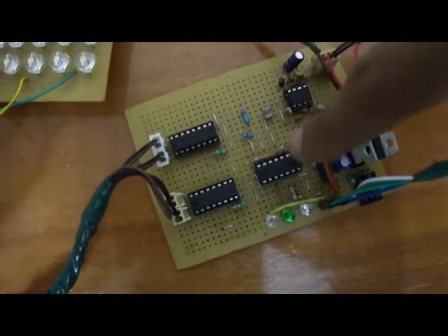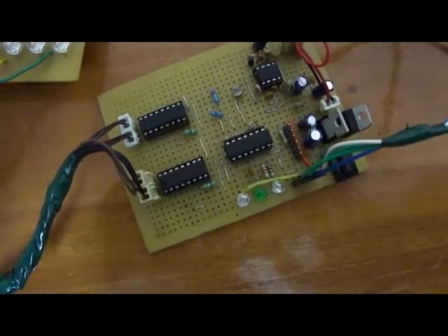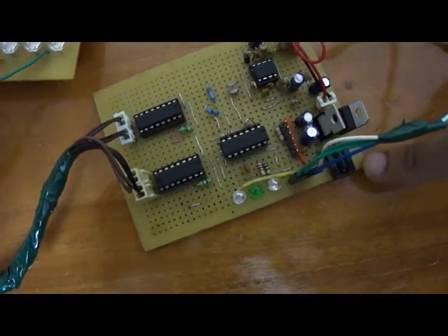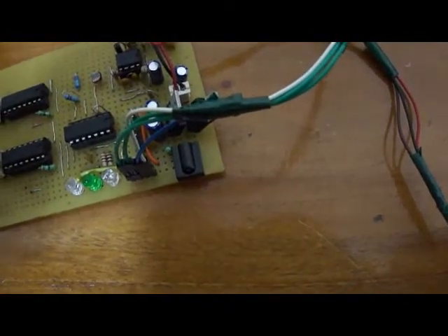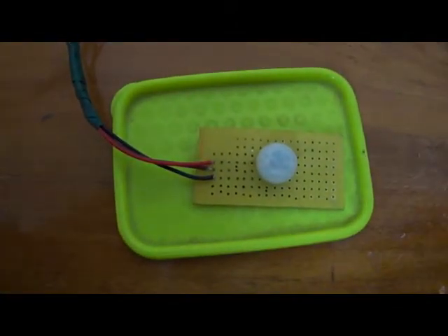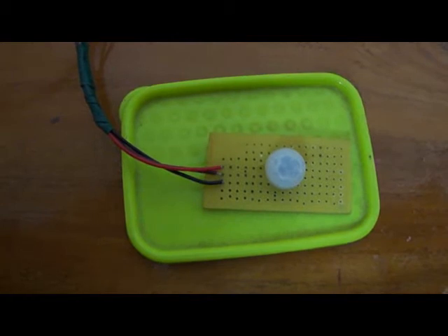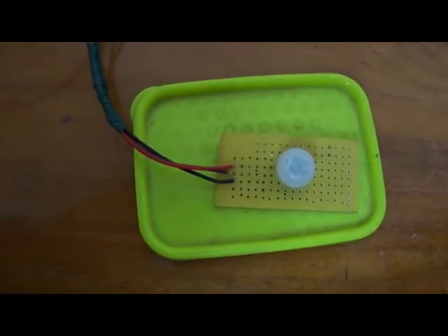The ADC of the MSP is connected to the LDR as well as the comparator's output. The TSOP1738 sensor here is used to communicate with the remote that we have built. We have a passive infrared sensor here to basically detect human motion. This changes its voltage levels depending on whether or not a hot body is present in front of it.